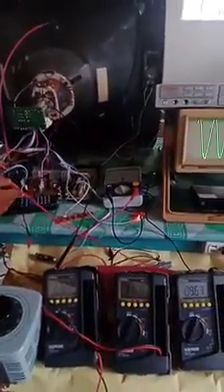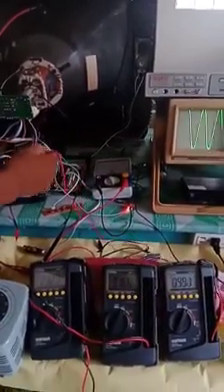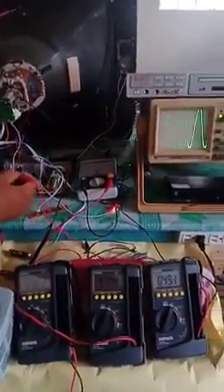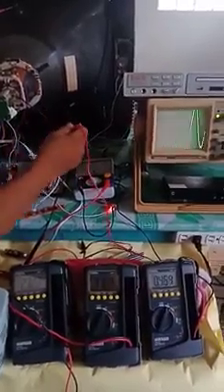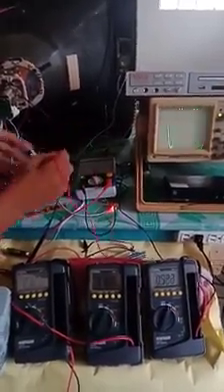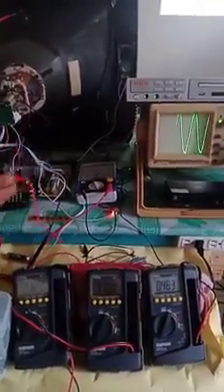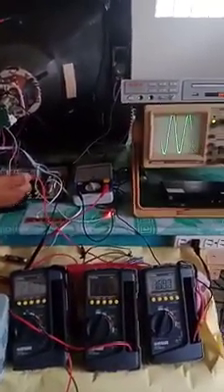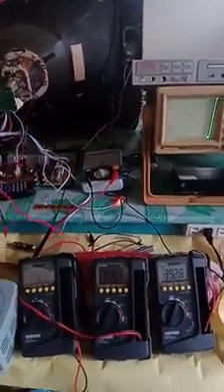For these TV receivers, the voltage for the collector, for the vertical out, and for the sound section are distributed by the low voltage power supply. We can also measure the voltage supplied to the digital circuit, because remember, this is not purely analog. There is an embedment of digital ICs also.